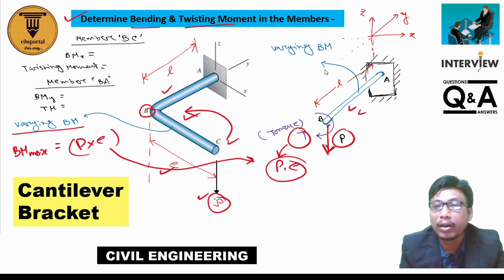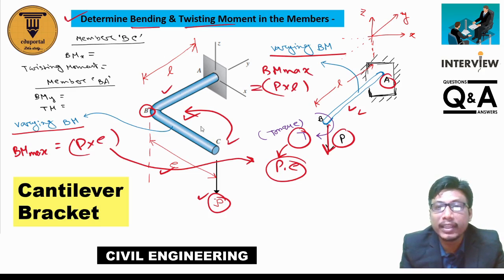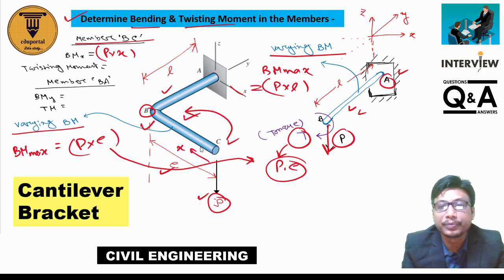So for the load P, there will be a varying bending moment in member AB, and the maximum bending moment, BM maximum, equals P into L, and it occurs at point A. So for member CB, maximum bending moment occurs at point B, and for member BA, maximum bending moment occurs at point A. For member BC, the bending moment is P into X, at any distance X from here, and no twisting moment for member BC.